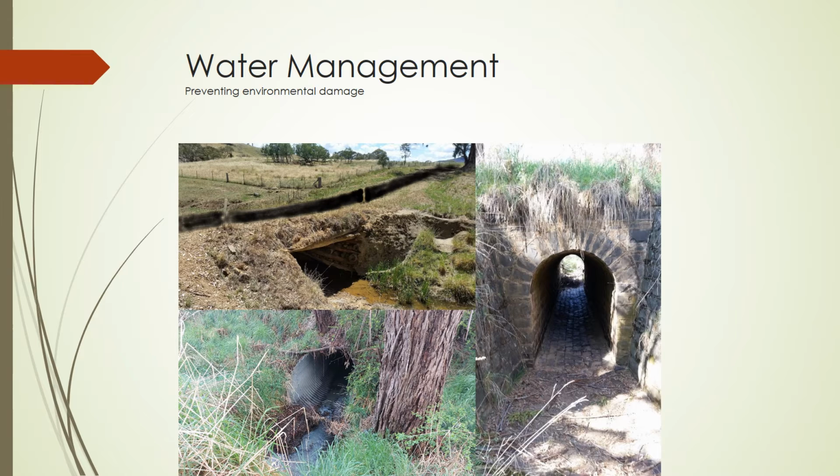Water management is a key aspect of any project, especially a build. The culverts that we're going to install will allow water to flow from one side of an embankment to the other, underneath the embankment, and typically over small creeks and low points. Care has to be taken when water flows so that the water flows well away from the road so that the road isn't damaged. Water is not a road's friend.